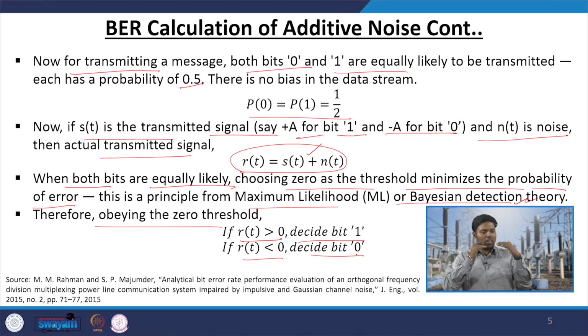So, depending upon what threshold value you are setting, generally it is set to 0. So, if you set that, then you see what values you are getting. Okay. If the value with the noise is greater than 0, then you set it at 1, and if it is less than 0, then you set 0. So, if you have some value and noise is added, and that value is already greater than 0, so it is already 1, okay. And with that noise added, that is further enhanced, so it stays at 1. So, you will not experience any bit flipping here.